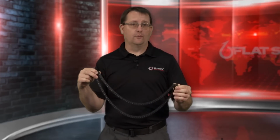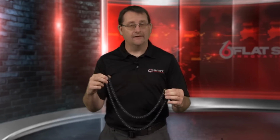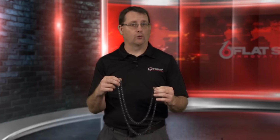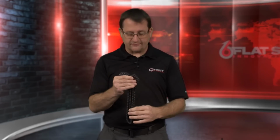Are most of the engines going to have that problem? No. But we normally see this in the earliest of 2002 996s. Those are the engines that lose timing chains more than any. Also, if you have a 2003 C4S or one of the more rare models, sometimes those engines were built in earlier 2002, even though they were a 2003 car, so they have the same traits. In those cases, this timing chain stretching will create a camshaft deviation issue.